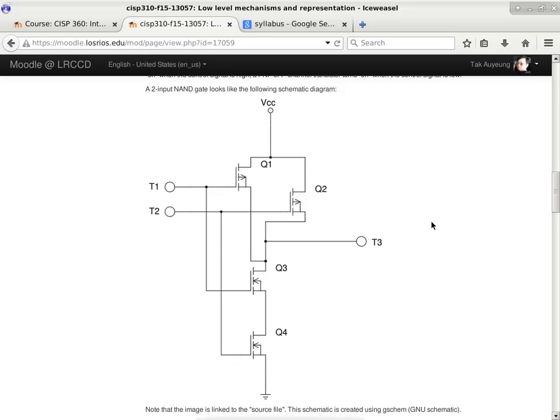What's the regulating mechanism? Like, if it's high voltage going to a P, why wouldn't it turn on? Because it will form a barrier. The metal oxide is separating the gate from the actual substrate itself. But by putting a voltage on the gate, it will influence the material in the substrate. So it will turn the substrate material from neutral to N or P, and as a result, it can form an opposing PN junction, so electricity won't be able to flow through it.